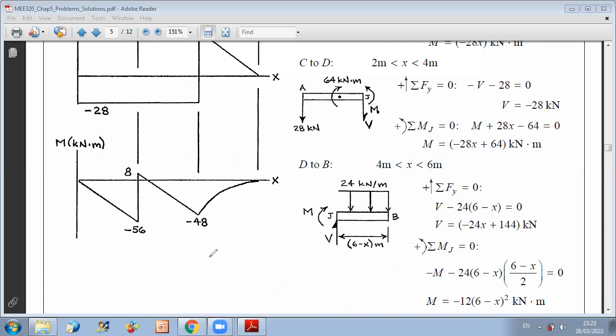Because, as we discussed together here, we want to calculate the maximum normal stress, and we know that sigma is equal to M maximum times c over I. Okay, and because c1 equals c2 here, since as we discussed you have a symmetrical shape, there is no need to differentiate between several cases.